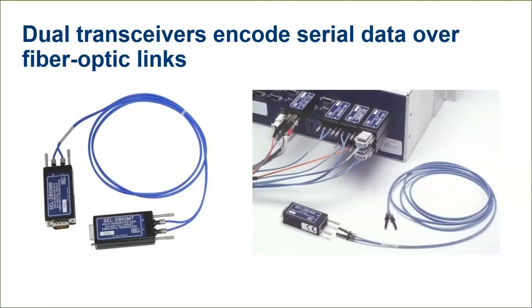optical link cabling do you have? Is it multi-mode or single-mode? The distance of the link, or how much power is required? Same as IRIG-B transmission equipment. Keep in mind with power requirements, SEL relays and other devices provide that 5-volt DC via pin 1 on any standard DB9 connector.